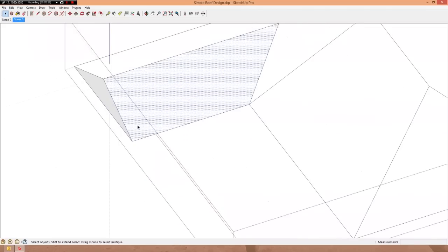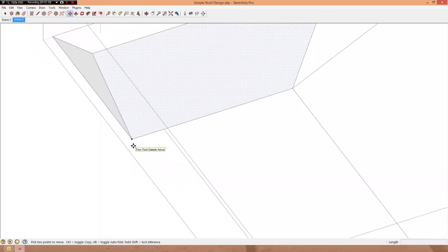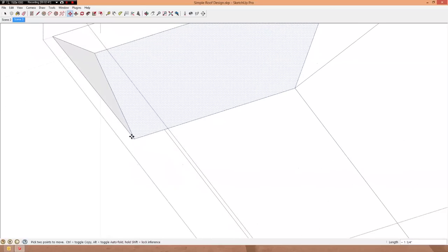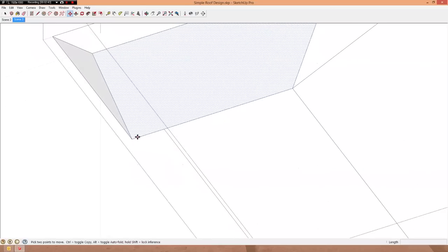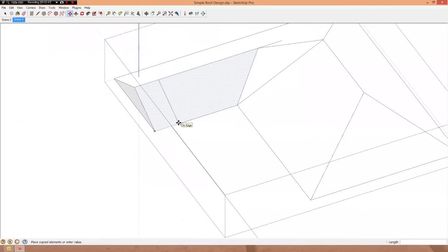this face is selected. I'm going to use the Move tool. I'm going to use a shortcut key to select it, M. Hold down the Control key. See the plus sign on the lower right side of the cursor indicating we're in copy mode now. I'm going to copy this face and drag it along so that it's moving in this direction, and drop it right there. So I've used this to extend it. Now I have two faces. I'm going to delete this edge, so this is one face.